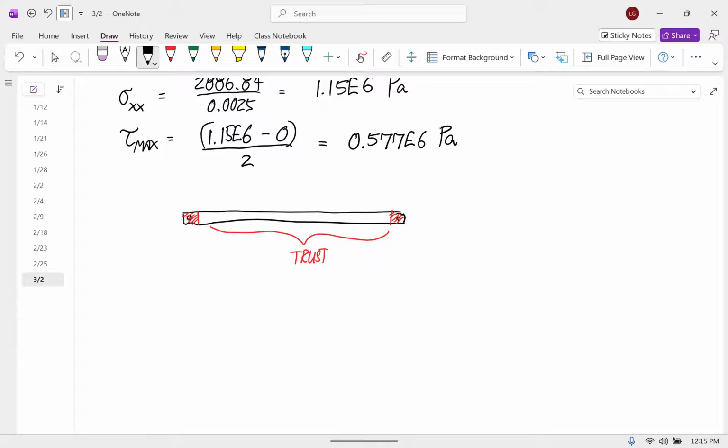So the results that we get, is it an interesting area? That's St. Venant's principle. The things are weird around where the loads happen, but as you get a little bit away from where the loads happen, the two equipollent systems' results match, but they don't match where the forces are applied. And if you did a finite element analysis where you were really calculating careful stresses, you'd get all these weird stress concentrations right at the pin and around it, but then everything would look normal again once you got away from it.